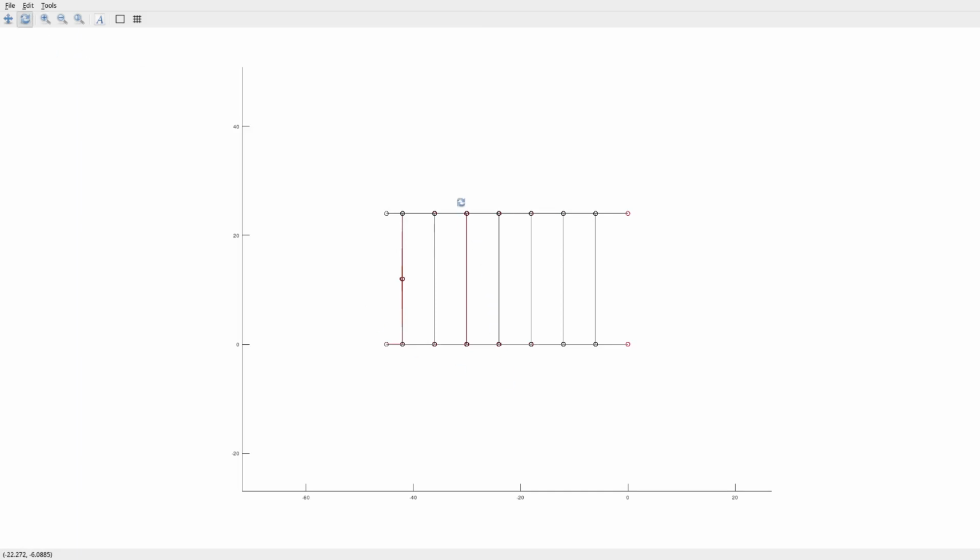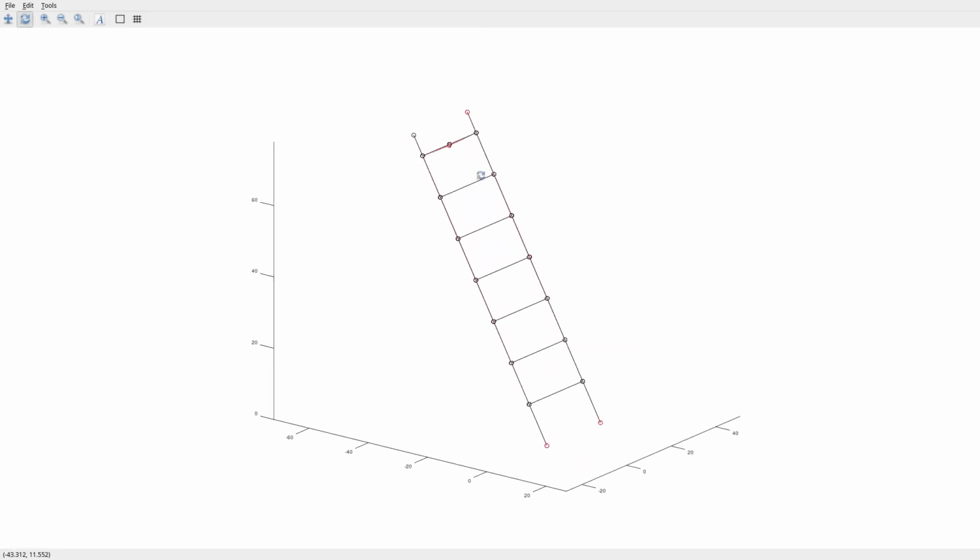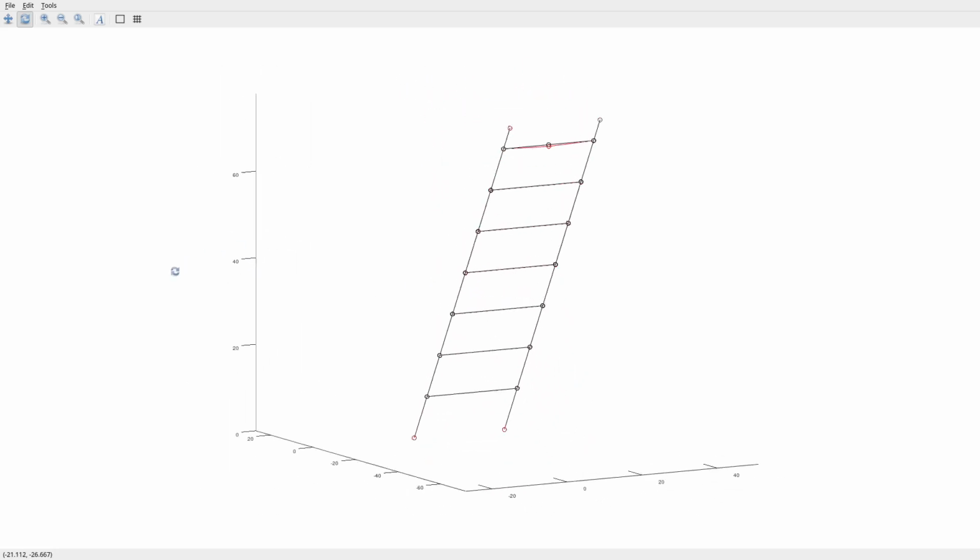But in reality, here's the thing. I'm just plotting the nodes and a line between them. In reality, what you have is a curve, right? And that curve is actually defined by those shape functions that I mentioned before in the bending direction. So you could go through and plug in an exact function that matches the slopes and matches everything at all these points using the shape functions that we talked about, and plot all these things. But ultimately, for this simple example, I didn't want to do that. But yeah, that's how this works.